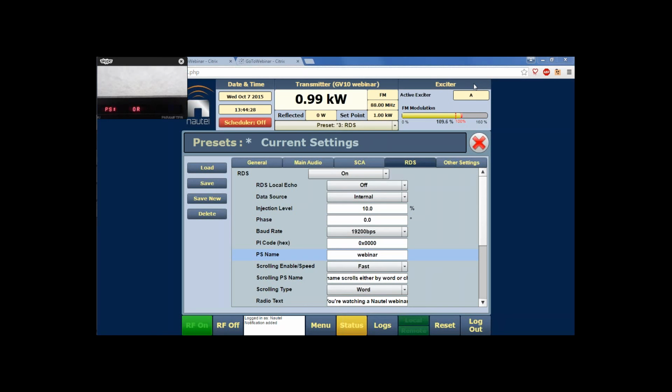We've got so many questions. Another VS300 LPFM question. RDS, for an LPFM that wants to avoid impairing coverage area, how much injection is required and how might that affect coverage? Do you have a location? What's that? Do you have a location? No. Because it's the same deal as running an SCA. You can increase your modulation by half your injection level. Yep. But coverage area, it's not going to make a huge amount of difference. X number of watts out is X watts out.